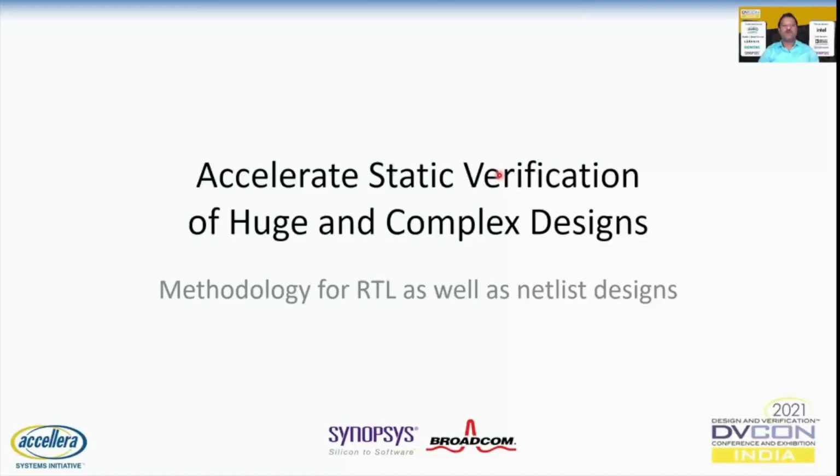Through this workshop, we are introducing a methodology for efficiently signing off huge designs for static verification. This methodology is applicable for RTL as well as Netlist designs. It is targeted for CDC, that is clock domain crossing, as well as LP, that is low power checks.